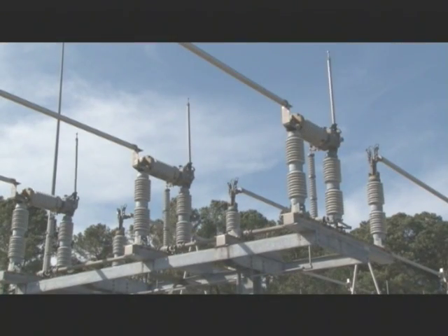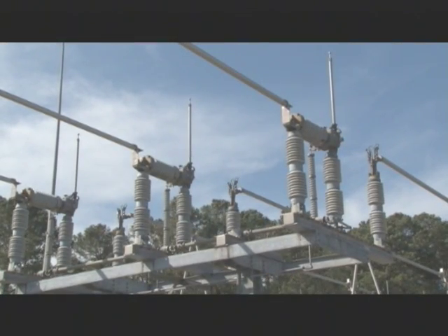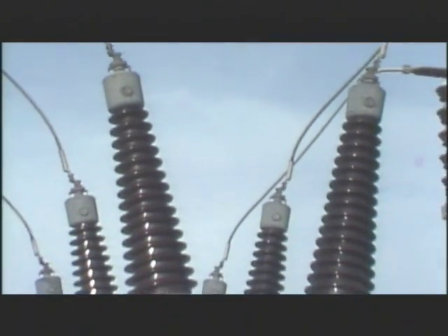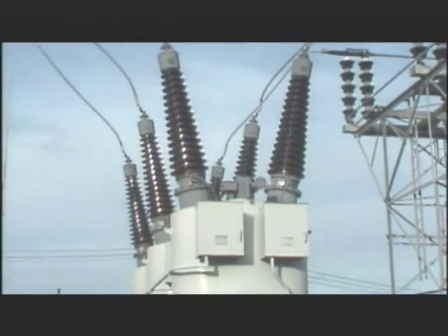If you're working on a circuit that's supposed to be de-energized, you'd open the breaker and the disconnect. That way, even if the breaker is accidentally closed by a remote signal, the open disconnect keeps you and the circuit isolated from voltage. Now we're going to take a closer look at some of the common types of breakers